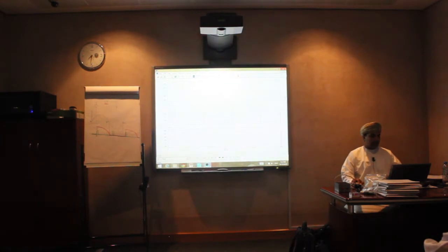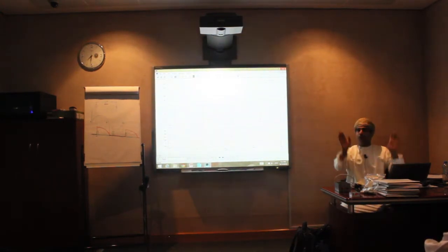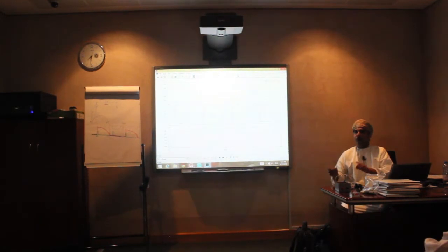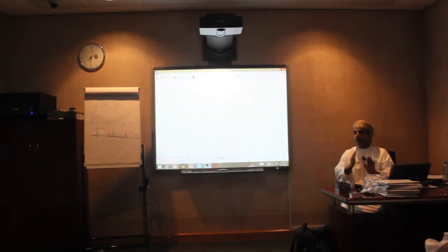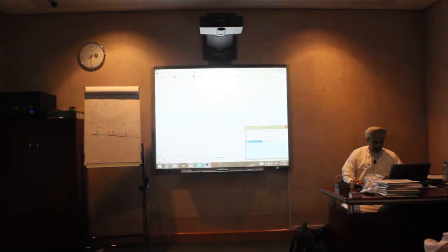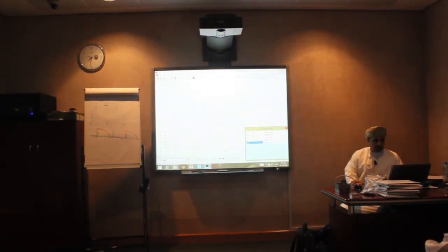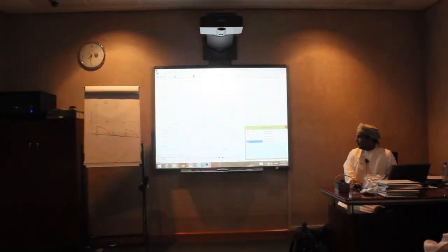Now, if you would like, for example, to operate the thyristor like a diode, put the firing angle alpha equal to 0. If you put alpha equal to 0, it will operate like a diode with higher average voltage. If you look at the average voltage, you can measure it from here. The average of V out now is 184 volts, right?